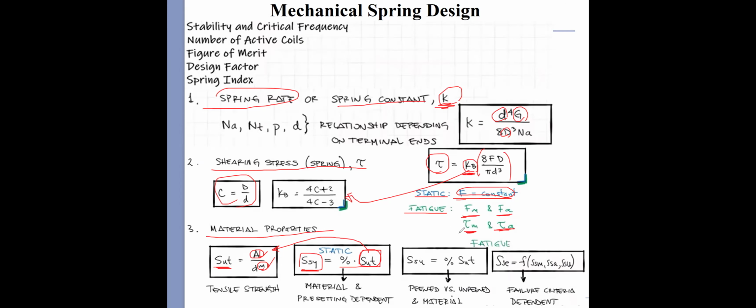We have to find its torsional shear yielding, which is a percentage of SUT. This spring wire might be processed with peening or unpeened, meaning its surface has been treated by peening or not.